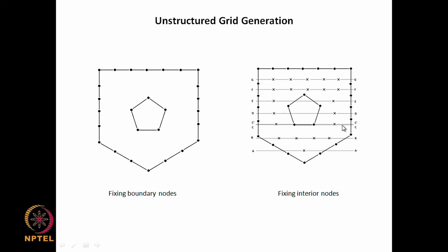So, in a case where I feel that the points are very close to existing points, then I can move the points up or down, because I know that it is not possible to get exactly the same length L all the time. It is okay to sometimes have 0.7 L distance or 1.3 L distance. So, accordingly we have to move the interior points around after using this general guideline to place them inside. Okay. So, this is one simple way for a 2D case of fixing this kind of domain.